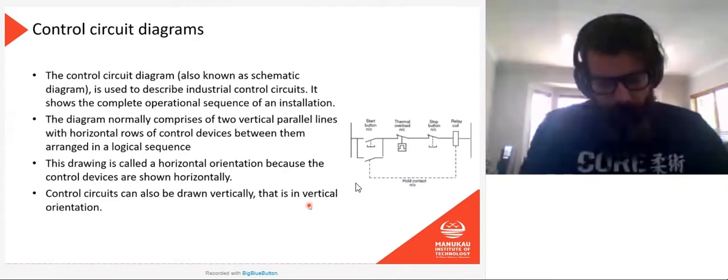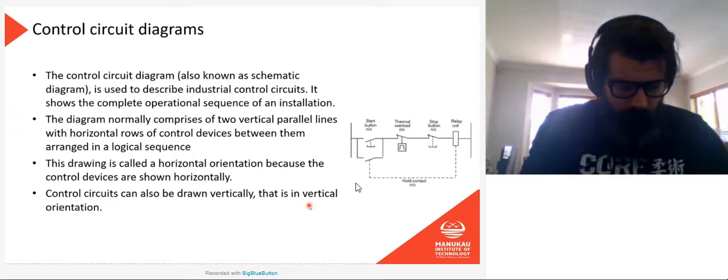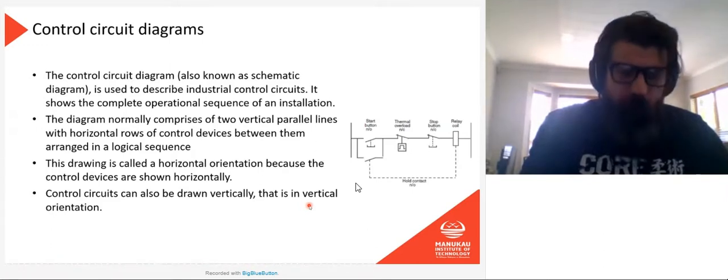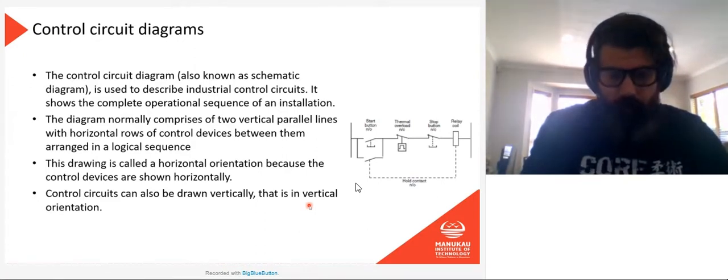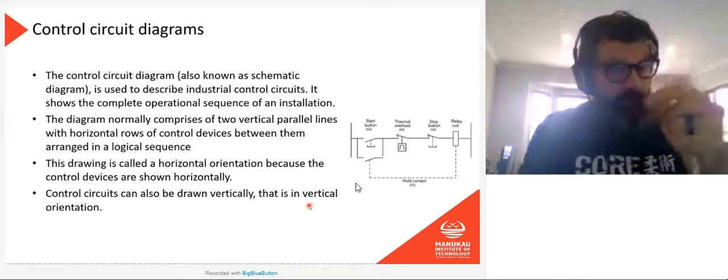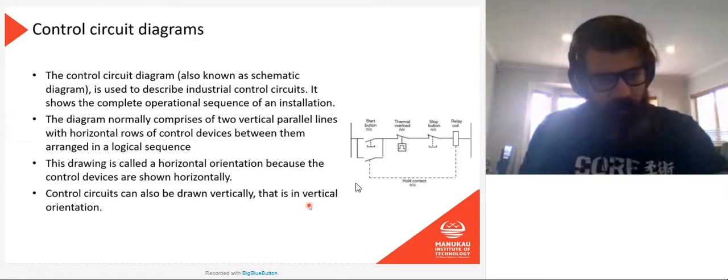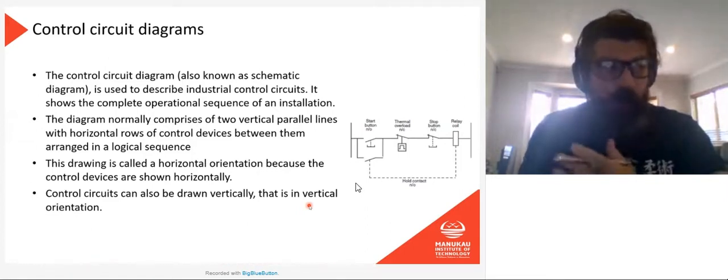A good example to think of here, which I talked about in our previous topic, is our emergency stop buttons and the start-stop buttons for our power in our practical class in 402. You'll remember that every time somebody pushes that button on one of the desks, I then have to push the button at the front of the class on the side of the switchboard. So those emergency stop buttons at the desk and then the push button at the switchboard, none of those are directly controlling the power.